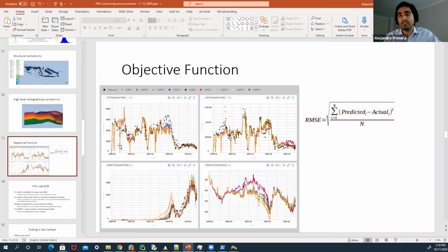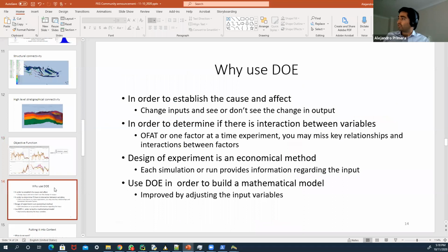What we would really like to do is run as many simulations as possible and later get a machine learning model to understand the effect of all the changes that we're making to the model, reading some variables and seeing the effect of those changes on those variables. In this case, for instance, the history matching quality, or the water cut. And that's what we want to achieve. So what I have done is use experimental design.